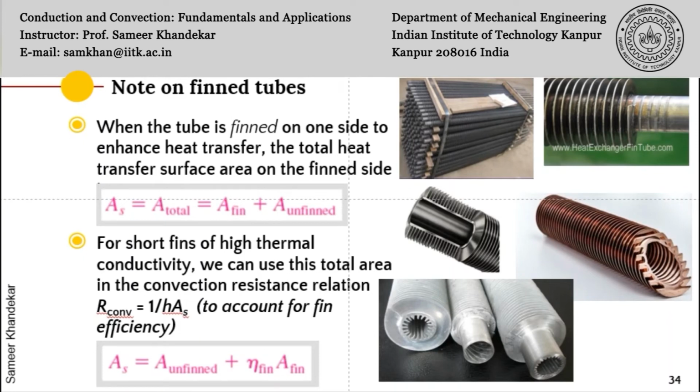I have tried to put many figures so that you also come to know that usually the heat exchanger tubes, especially when you are using a gas or air, will always have some fins. Now the fins may also sometimes be inside, because you may have a refrigerant flowing and you may like some turbulence also, and some extra fins. You can see here that the fins are actually inside as well as outside.